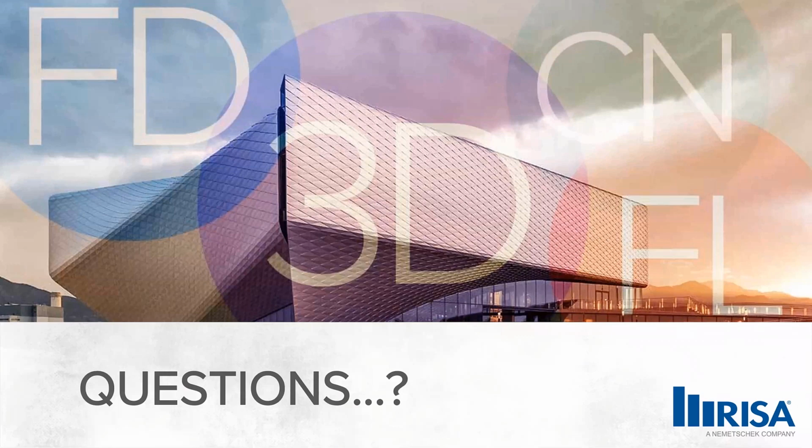So let's see. Does RISA 3D design for out-of-plane and in-plane seismic loading for concrete walls? For concrete walls, it does include both in and out-of-plane loading. You can define those walls as special shear walls and it will denote whether or not you need boundary conditions. It's not going to design those boundary conditions, but it would tell you whether or not you need those boundary conditions for those walls.